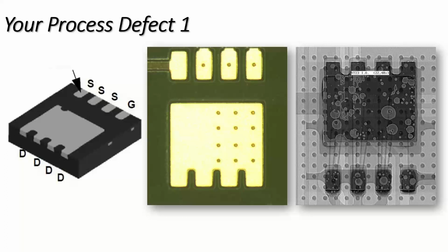So if we look at this first example, he hasn't told me about the stencil design or any of those nice things, but I assume that he's using standard design rules by breaking up the footprint. But the first thing that you see is vias. Now, these vias are filled and plated vias. So he's filled them, he's plated them, and there are other examples on the board. But still, one of the reasons why we can get voids is outgassing from vias, and that can still happen even though they're filled and plugged.